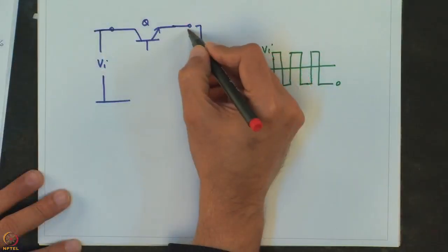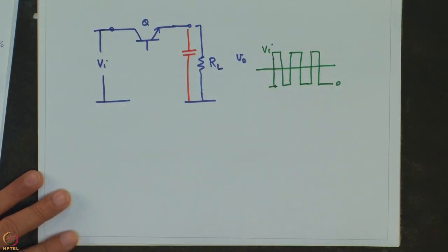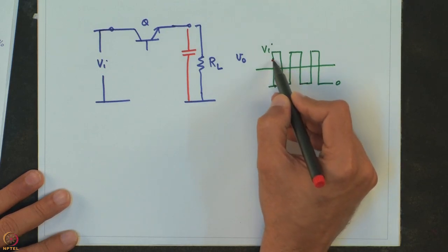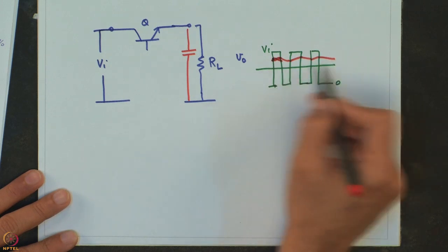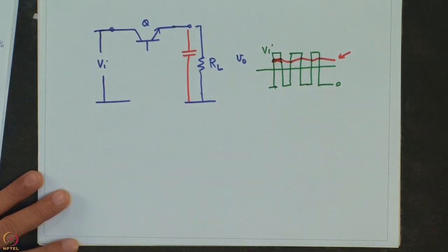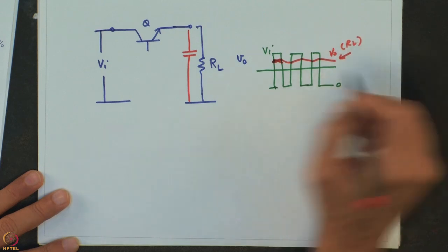So what we can do, somebody would obviously try to add one capacitor. If I use a capacitor, depending on the frequency at which these waveforms are going up and down, my capacitor value will be chosen, and it will definitely make this maybe something like this. It will go like this, like this. So this is what we will get. Okay, and the more the value of capacitance, the less will be the ripple in this voltage. So this is my VO, which is across RL.